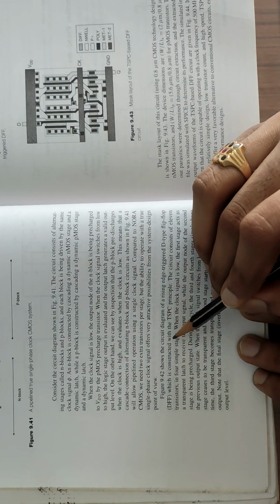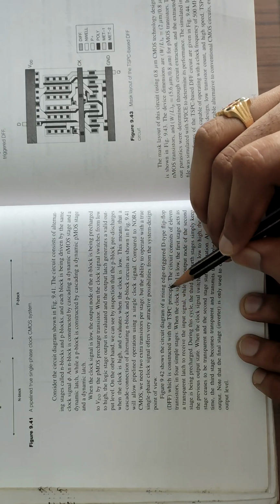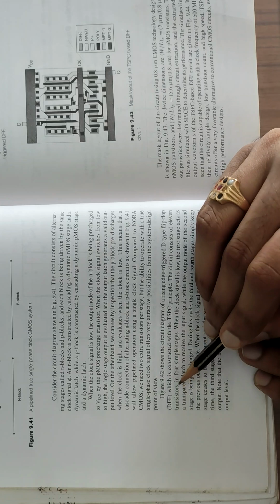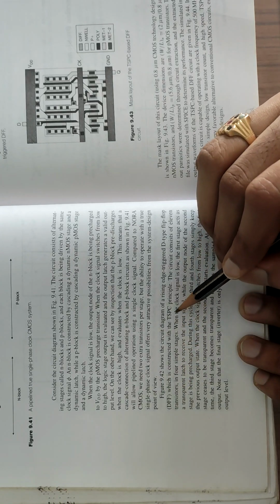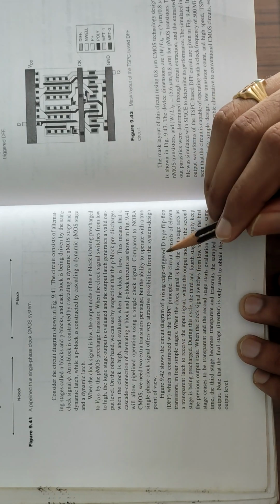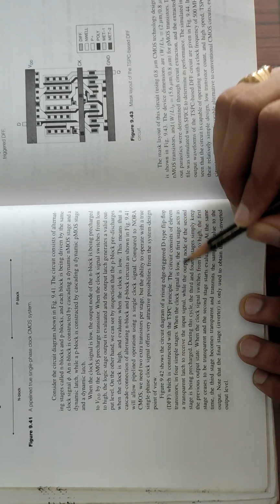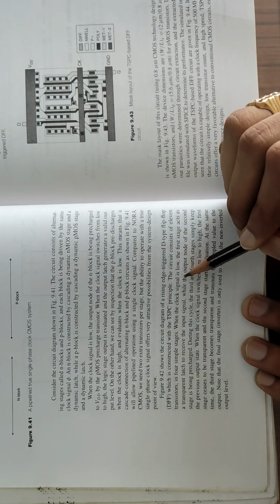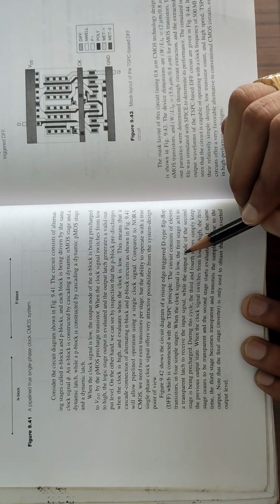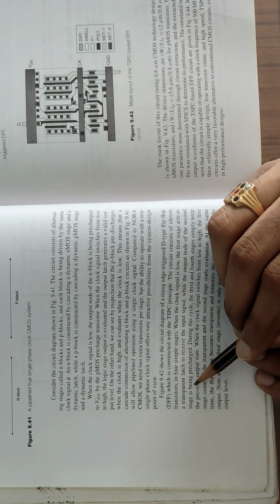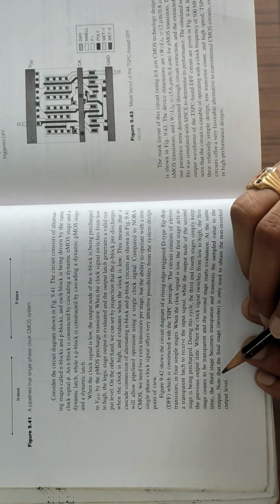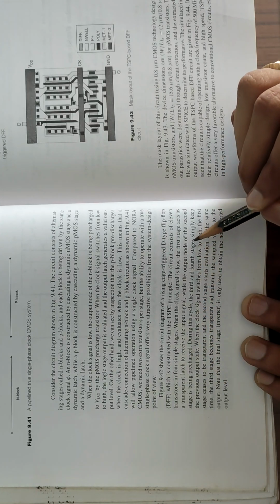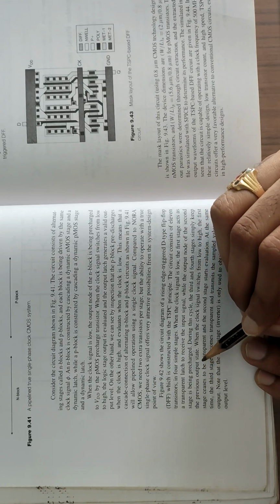The figure shows the circuit diagram of a rising edge triggered D-type flip-flop, DFF, which is constructed with the TSPC principle. The circuit consists of 11 transistors in 4 simple stages. When the clock signal is low, the first stage acts as a transparent latch to receive the input signal, while the output node of the second stage is being precharged.